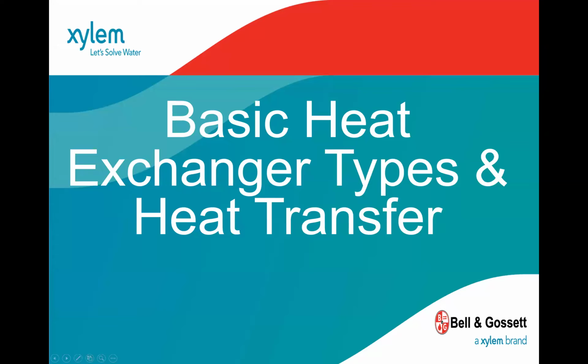And so you often see, as allowable pressure drops go up, the size of the unit goes down. What that boils down to is really you need to find the sweet spot for your application. Another thing we'll mention a few times, there's always a trade-off for something. Let's say we decrease our upfront cost by having a smaller heat exchanger, by allowing higher pressure drop; well, our operating costs are now likely going to increase, right? So as system designers, what we have to try to do is have at least a grasp of all of the variables that we're having to balance for the best solution. So just keep that in mind.